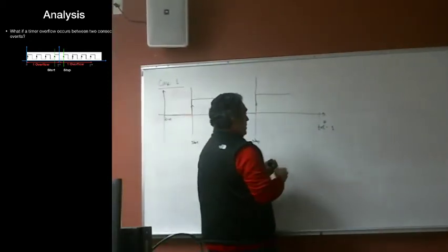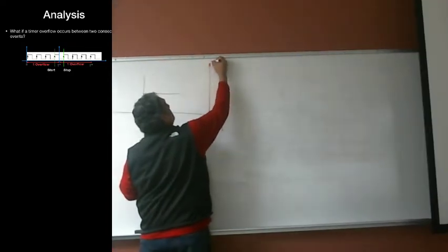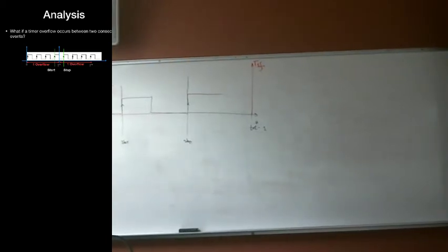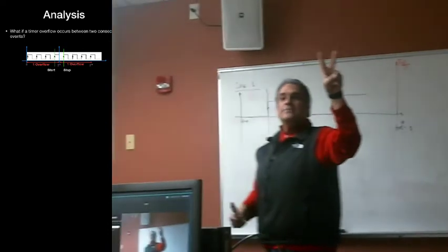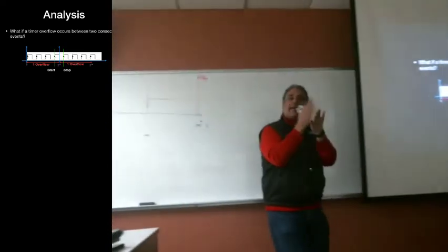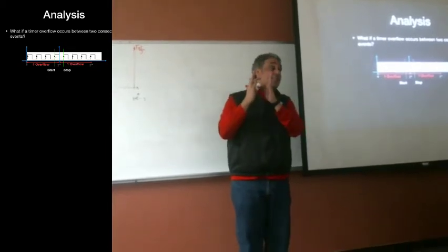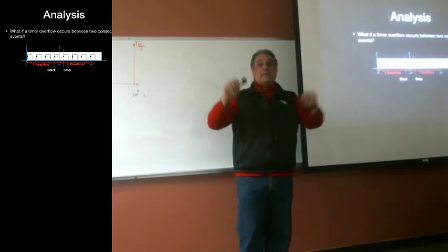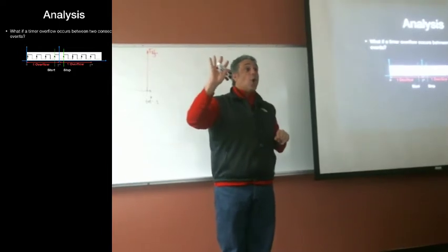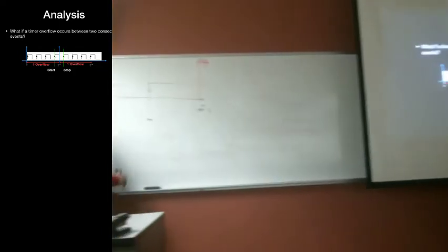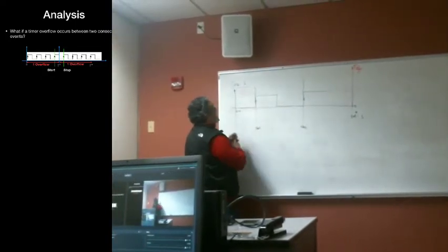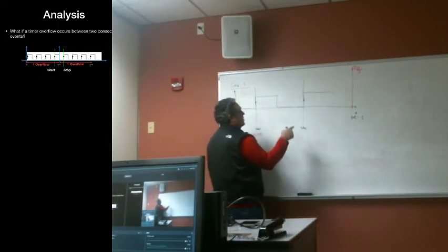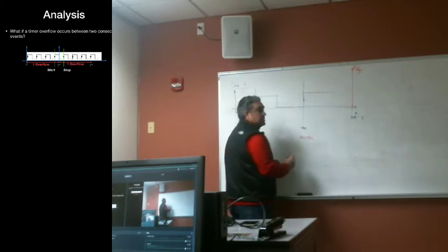So that means the timer 1 overflow happens at that spot in time. You have 2 circuits working at the same time. Timer 1 is just going tick, tick, tick, completely independent of CCP. Capturing and comparing on one end, the timer on the other. The timer is always running, and the capture circuit is working underneath. The first time this hits, this information is going to go to CCPR1, and when this one hits, that information also goes to CCPR1.